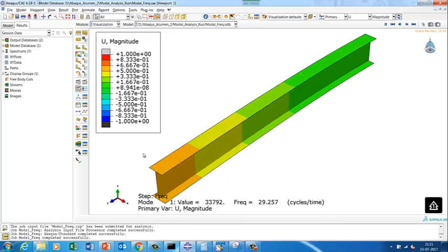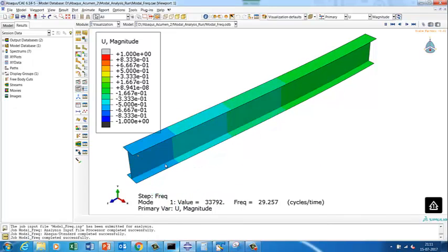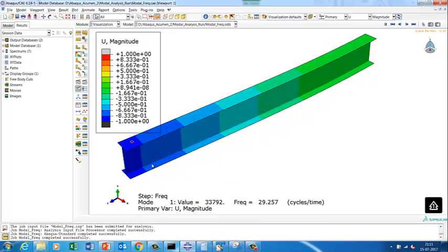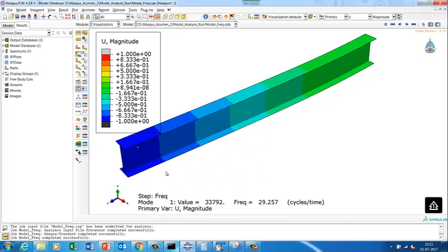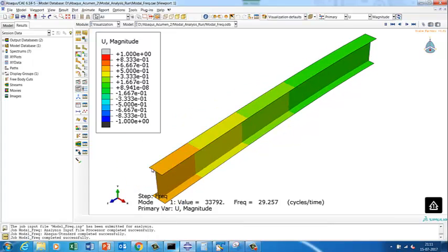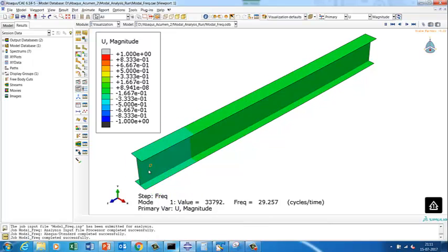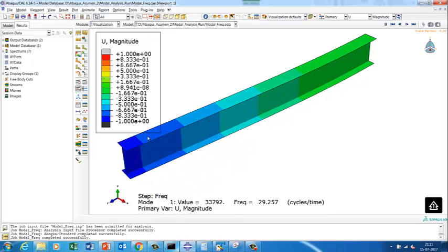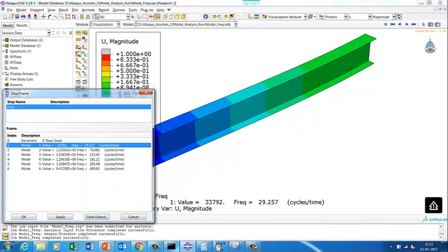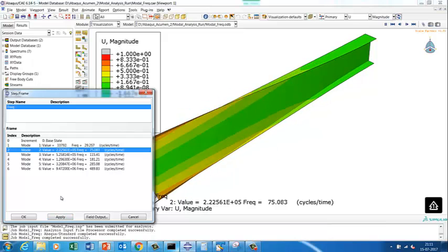In the lateral direction you don't have much stiffness. For the I section, the major stiffness is in bending, against the I section. So this is the lateral bending, because it's not perpendicular to the I section. This is your first mode. So the first is a lateral bending.